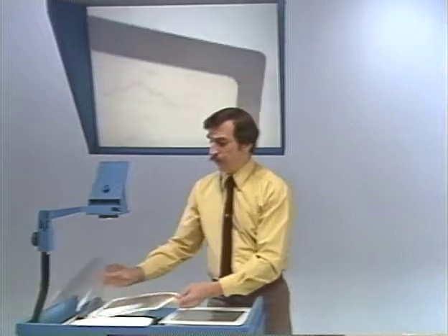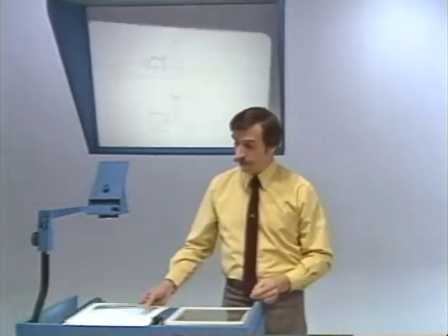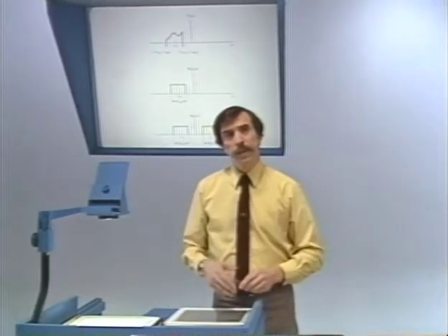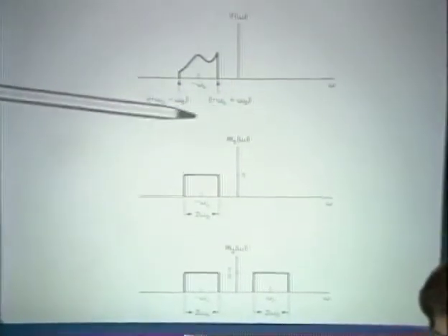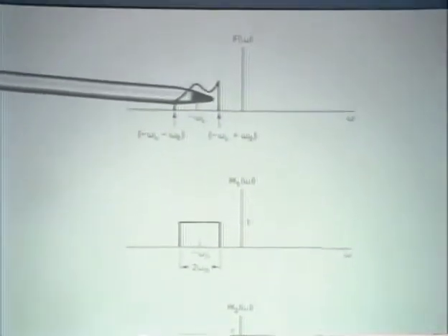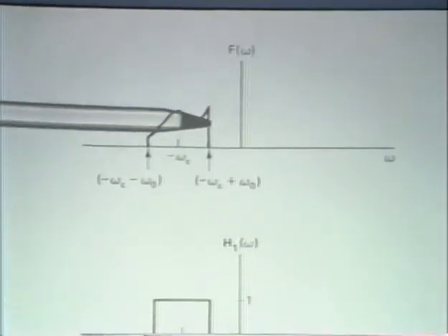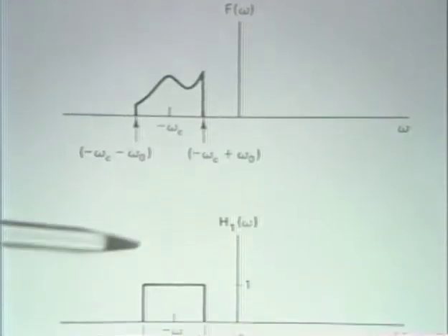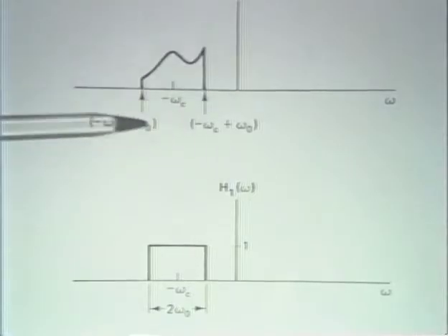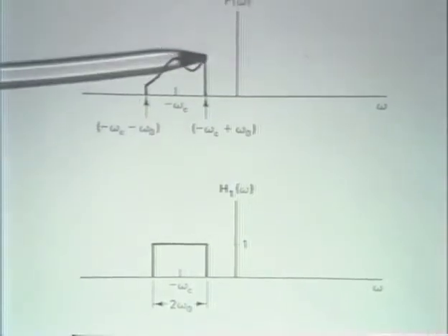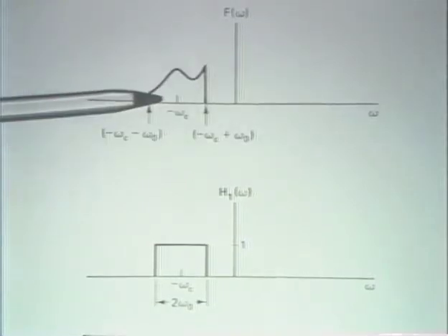So in terms of tracking through the spectrum and looking at the equivalent filtering operation, what we accomplished was to pull out this part of the spectrum using a low-pass filter and modulation, but equivalently what we implemented was a bandpass filter, as I indicate here. Now, of course, a signal with this spectrum, since this spectrum is not conjugate symmetric, we know that this signal does not correspond to a real valued signal.